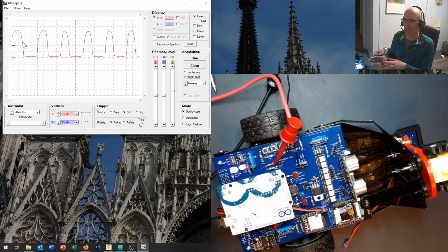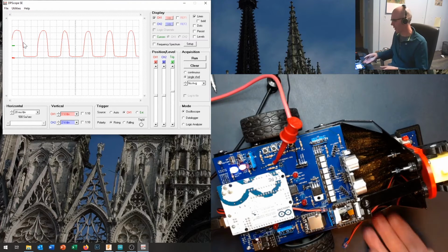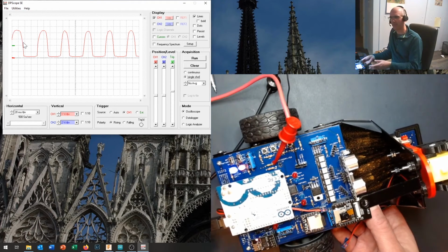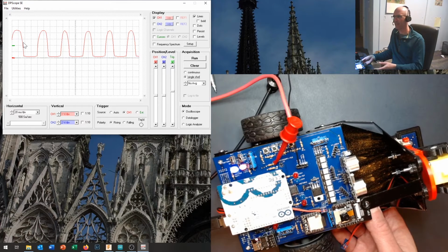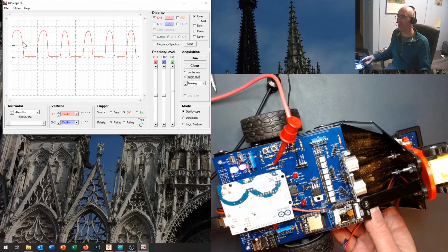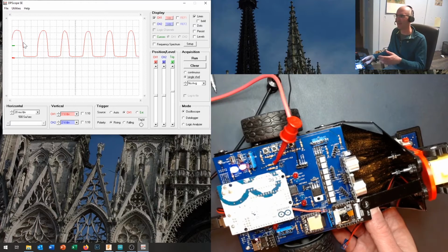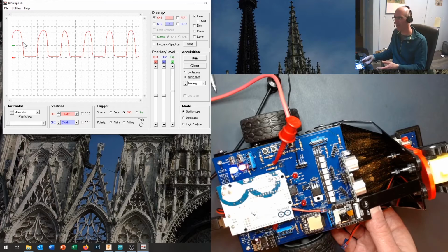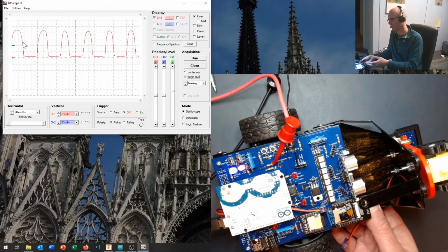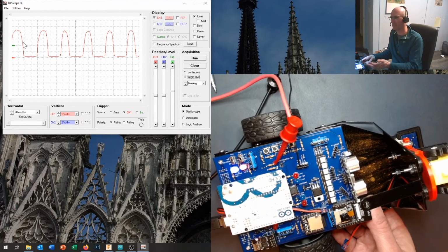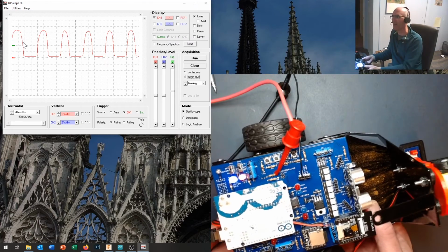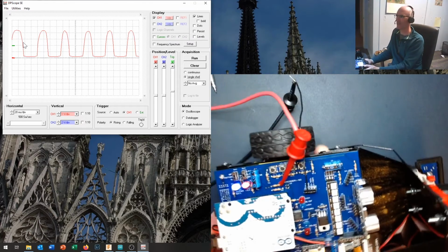Now, one of the reasons that this works better than time measurement for managing your robot is that sometimes when you're running the robot, the batteries will start to die. You're trying to do dead reckoning and you go out there and you've got a really supercharged battery, so you're traveling a little bit faster than when you did using your slightly dead practice batteries. So using time measurements, your positions can be all the way off. Maybe there's a headwind. Maybe your motors aren't quite as low friction today. Maybe all these different little differences. You're on a different surface.